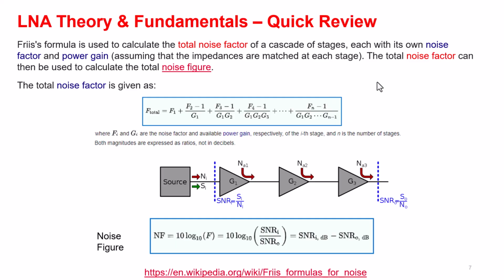So if you look at the Friis equation, which gives you a pretty good idea about cascaded noise figure, as you can see, the initial few stages contribute the most in the overall noise figure of a receiver. So by controlling the initial few stages, you can control the overall noise figure, which goes a long way in your receiver working more effectively.